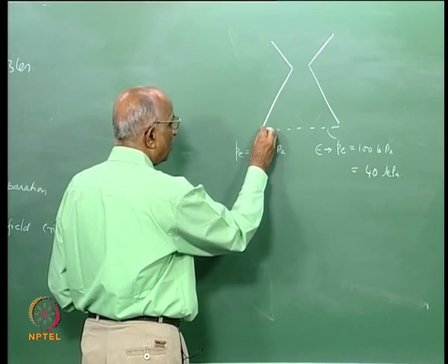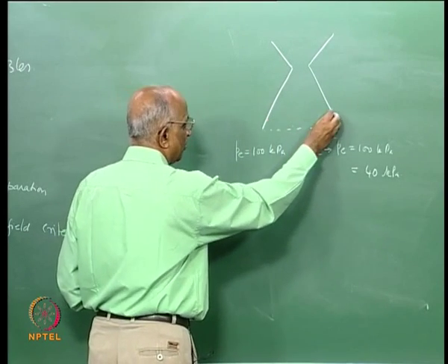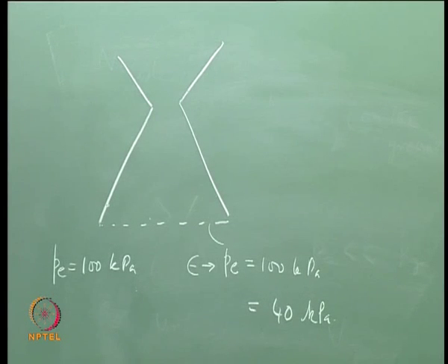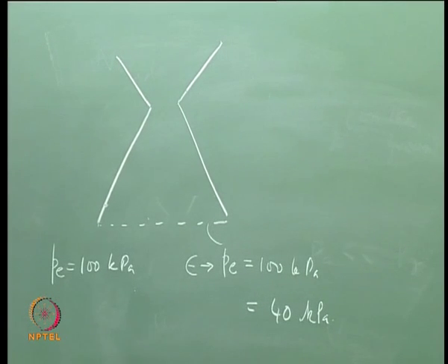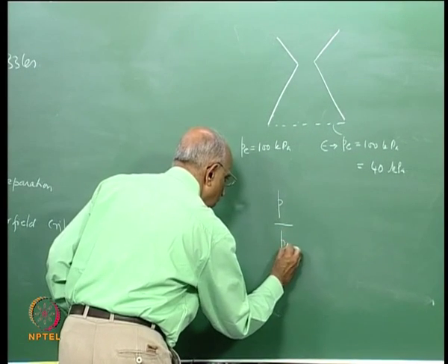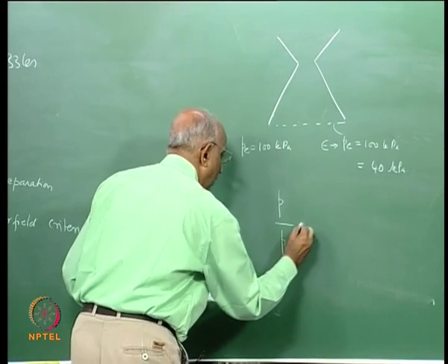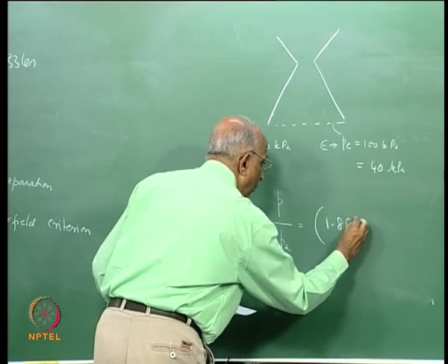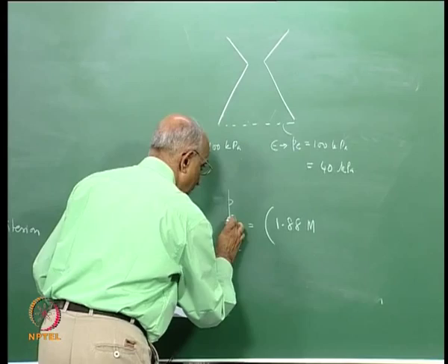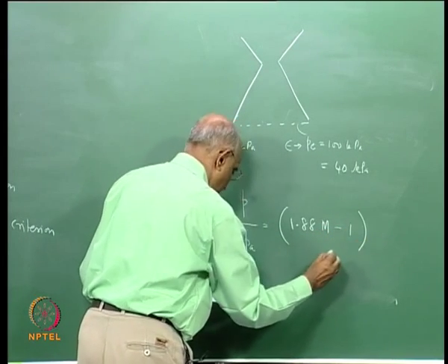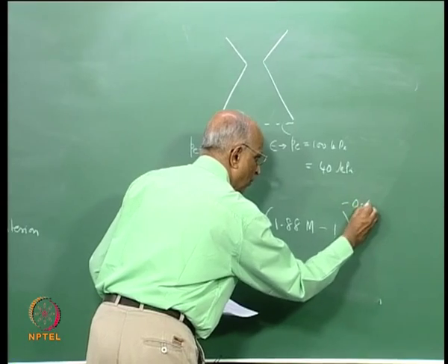Having said that, this is also not perfectly right. In fact, the local Mach number at the zone of flow separation affects it, and the value is given by P by Pa equal to something like 1.88 into the Mach number at the plane of exit, or wherever you want flow separation, to the power minus 0.64.